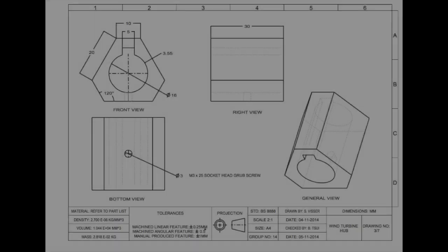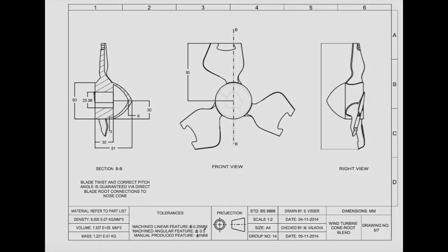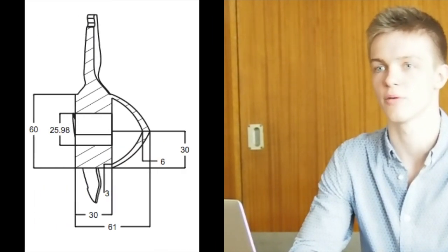The merit function could be significantly improved by reducing weight. This could be done by further reducing the hub's length, the thickness at the roots, and especially the cone size, as these were the regions with a lot of excessive material. Ideally, one should also anticipate the removal of 3D printed support material from the inside of the hollow cone, which adds weight and results in the turbine imbalance.